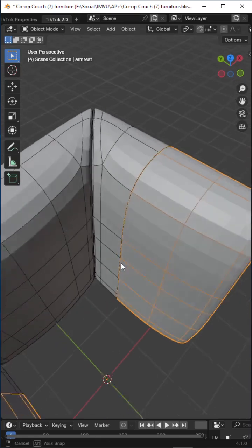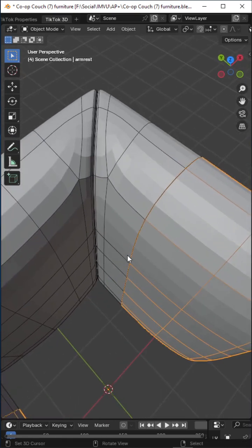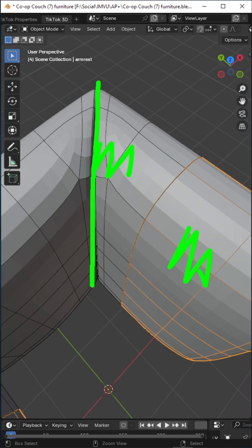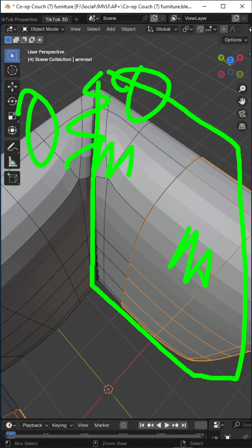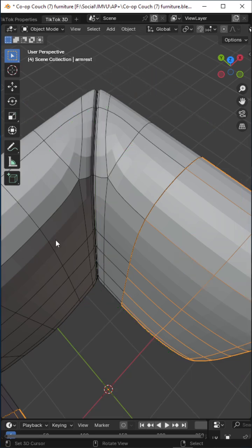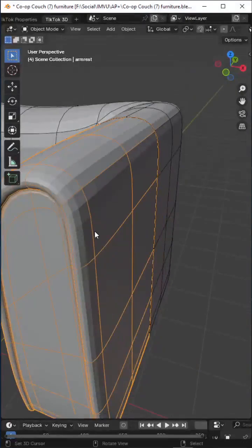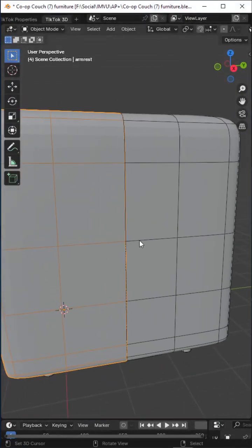So in other words, what you're trying to do is mitigate the amount of work that you have to do in order to join. So this is a separate mesh and this is a separate mesh. If this was one entire mesh, it's much more difficult to join this to this at this corner than it is to join this entire mesh to this in the middle, where it's just a straight line. So when you're making your meshes, you want to think about things like that.